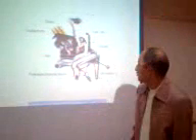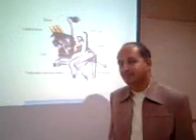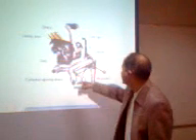From this end, the slivers are fed. At one time, you can feed different materials. Say you can feed cotton as well. Along with cotton, you can feed glass fiber, or you can feed some other high performance fiber. The material is first opened. Then there are two rollers. These two rollers have air suction in them, which condense the material on them and then produce a yarn, which is delivered in this direction.